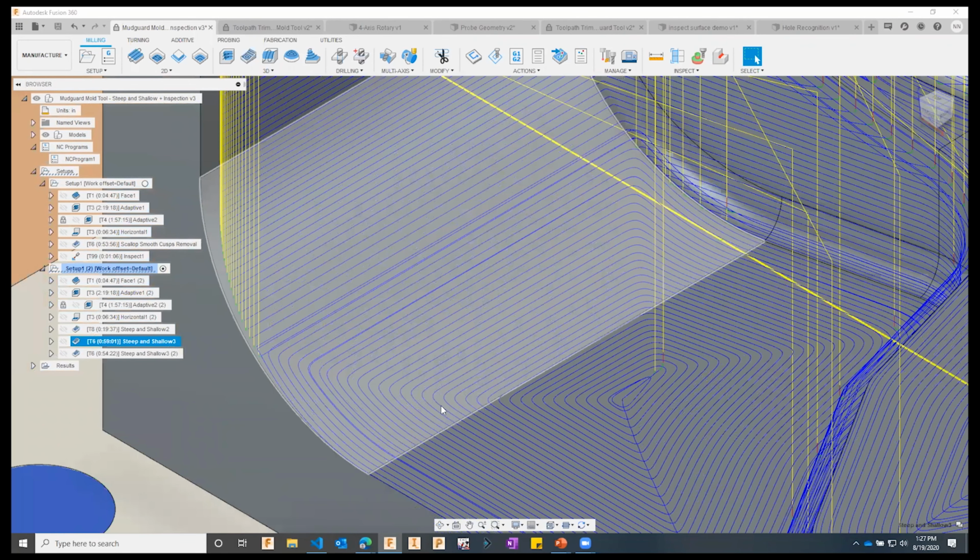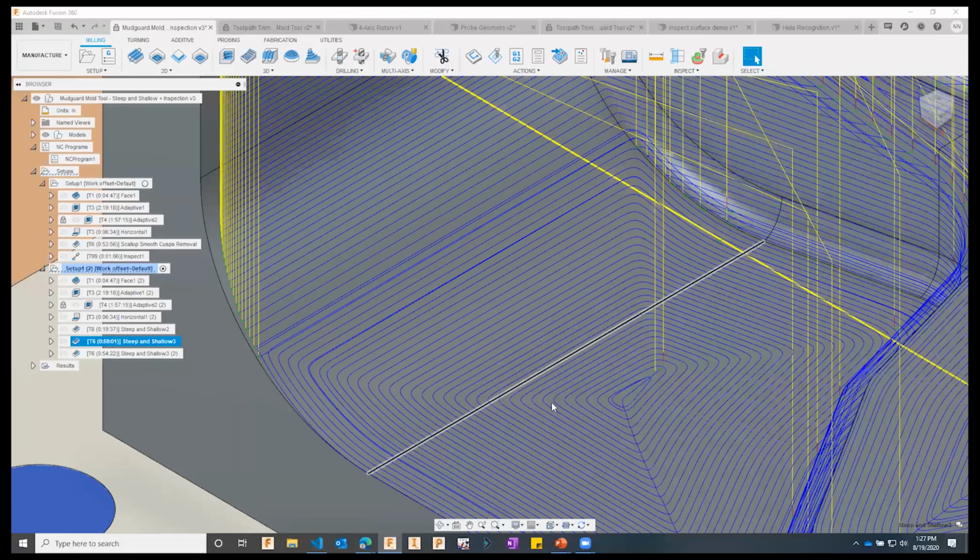It's all one continuous toolpath, so we'll have a better surface finish because we're not leading in and out of the material a bunch of times. But also, we have these corners smooth. Whenever that toolpath has to collapse, it's not coming to a point. It's coming to a nice smooth that keeps the cusps down just a little bit.